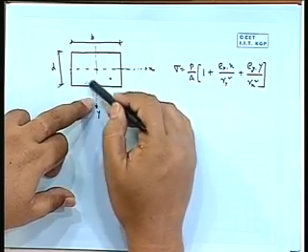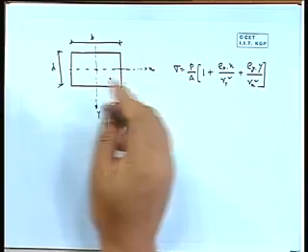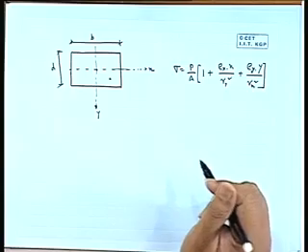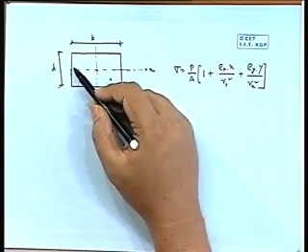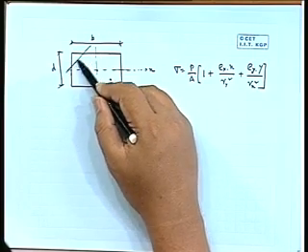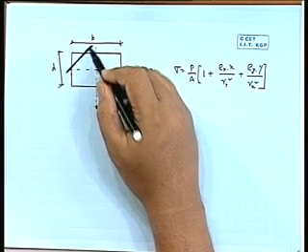Now if it is here, so the 0 line will be along this, right, because there is a moment in that direction, resultant moment. So there will be some line that will have a 0 stress. Beyond that, it will be tensile stress, and this side it will be compressive stress, right. Now, so we can pick up any Ex, Ey, there should be some line. So this side will be compression and that side will be tension, and there should be a limiting line.